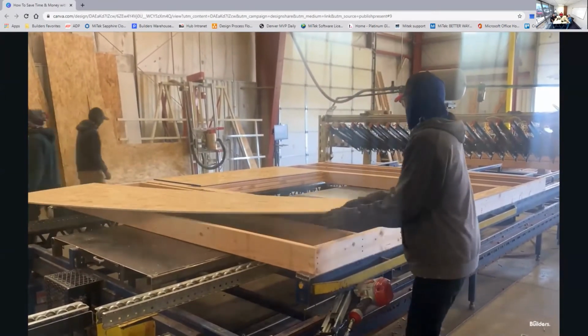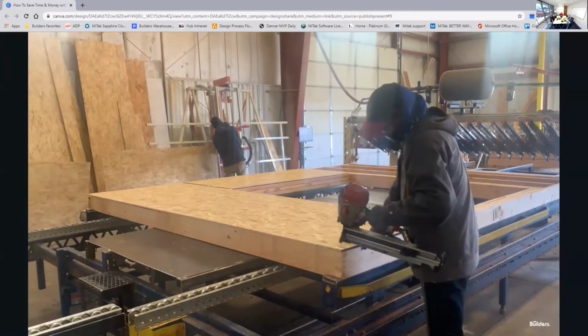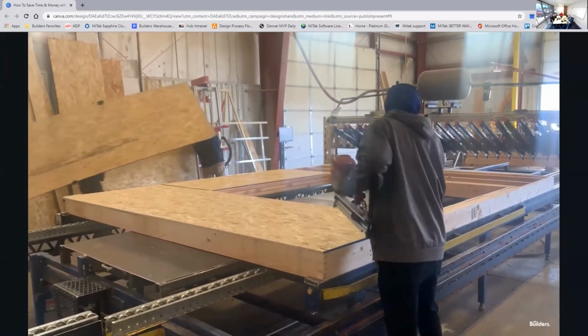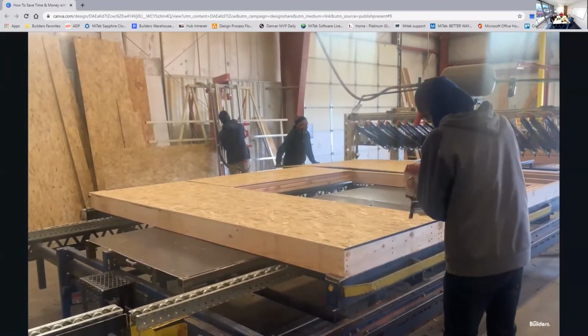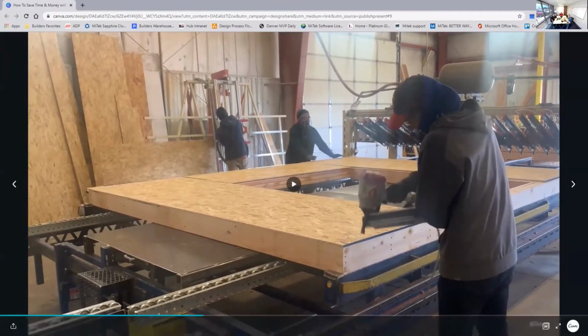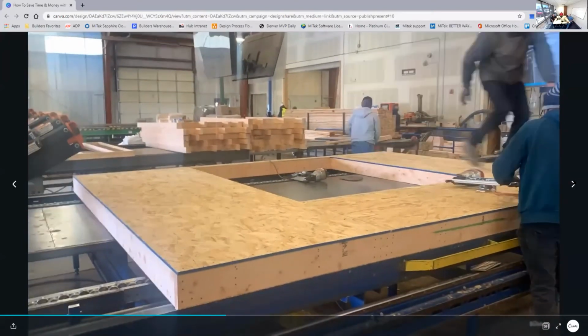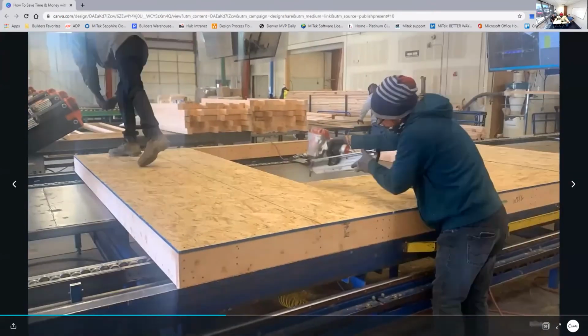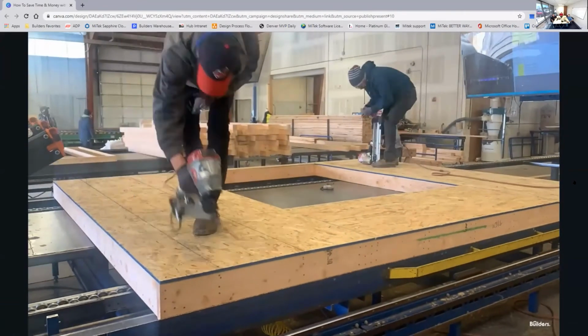So it tells them how it needs to be nailed, the on-center spacing and things of that nature. It's literally at the detail of every nail is specified out, and we build it to those specifications. We'll watch a fast forward review of them nailing it off. So they go through, they're chalk lining, so it's nice and straight. That's what they're doing there.